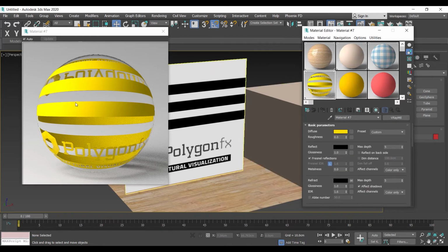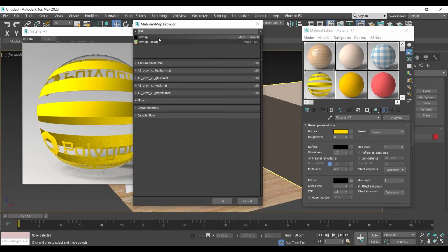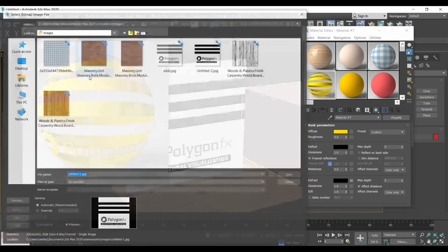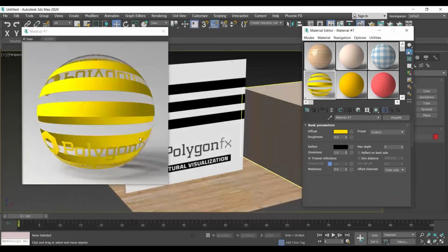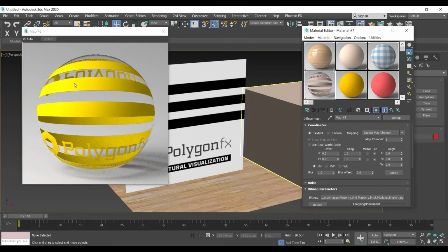And I have some places with which I can find this texture. And other places I can find this color in my case, or other places I can see it's transparent. I can just change the color in here, or I can import another file. I can just import a bitmap, which is, for example, instead of having color black, I want it to be maybe brick. Now it will become brick in here instead of the yellow, because I inserted the texture now. So we have to wait till it loads. So this is my brick. I can just do the tiling for the brick. Maybe I want it to be 3 by 3, make them smaller.